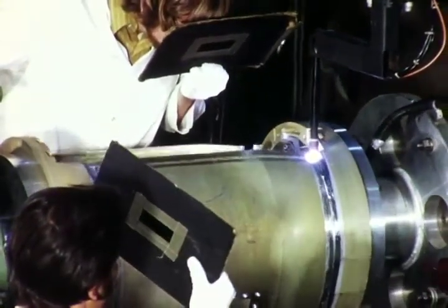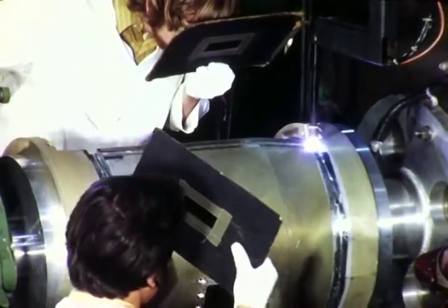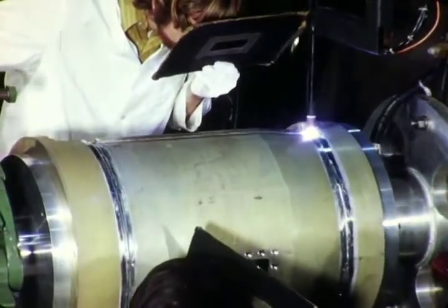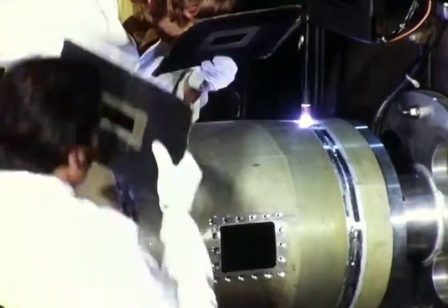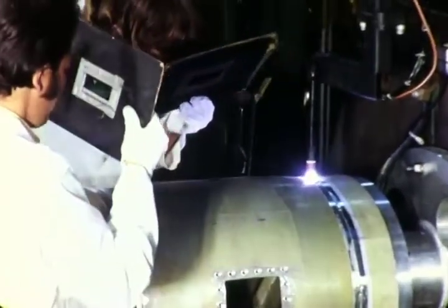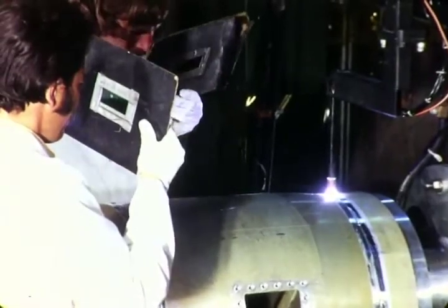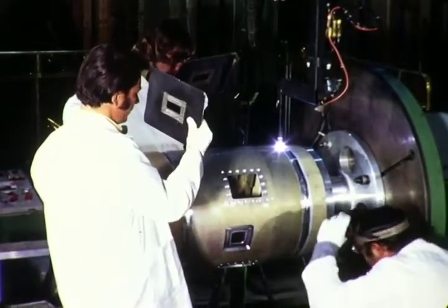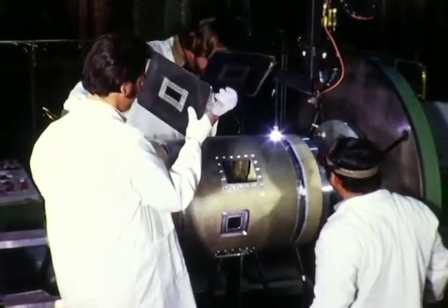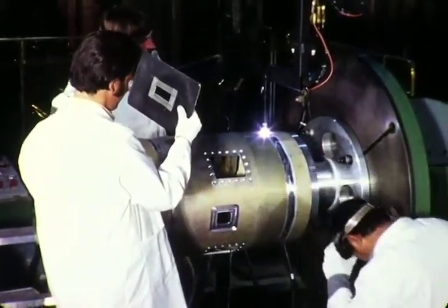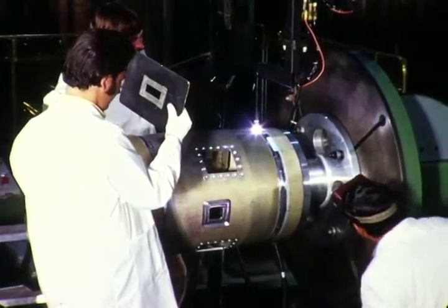The weld thickness increases in this area, calling for a programmed slowdown in table speed and increased welding current. Overall thickness of these weld joints varies from less than a 1/4 to about 3/8 of an inch. By making these welds in a single continuous pass, distortion in the assembly is held to a very low value.